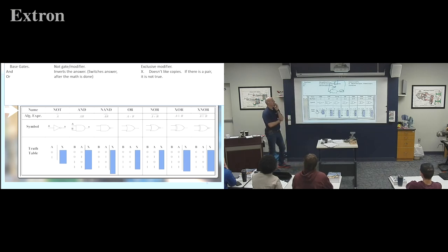What gets a little bit tricky is if you wanted to draw it as a NOR gate, and you go, ooh, how do I reverse this? It'd be actually kind of fun homework. To reverse it, we could have our input come out and go through the coil of a contactor, and then the contactor, if the coil is energized, would open.